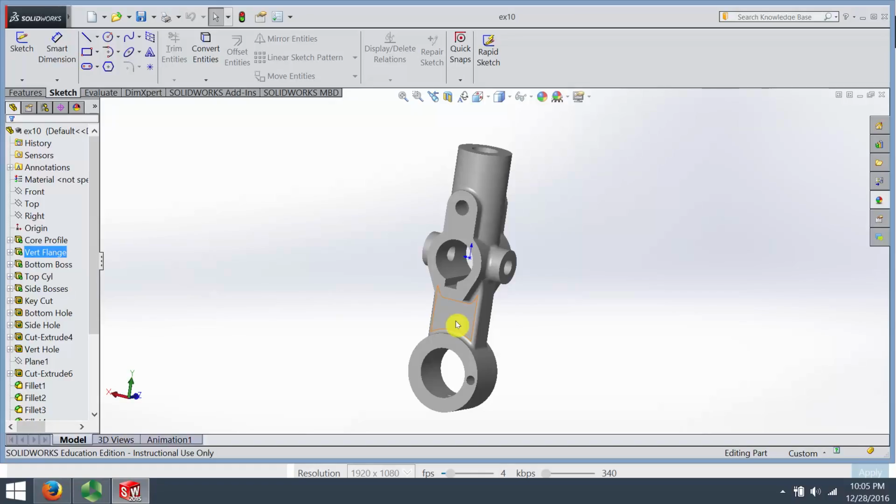and then start working out from that engine block with all the other componentry. Now keep in mind as I go through this, I'm going to stay within the top-down model system, or within the in-context system, that I'm going to model all these parts in the context of the assembly, just to keep it simple. But there's no rule about that. If you've already modeled parts, or you're downloading parts from some website or from another user someplace, you can totally just go in those and insert those and mate them just like you're used to. This is for the parts where it warrants it. It really helps to, I call it growing the parts, almost organically growing them off of some main features.